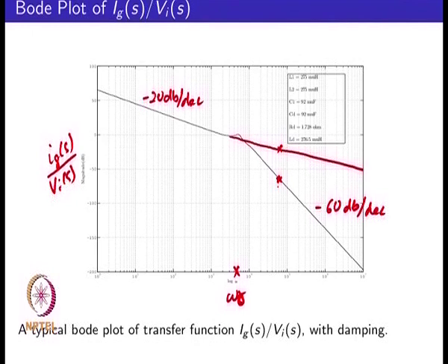So you know that it is feasible to meet the attenuation requirement suggested by the specifications with the LCL filter. What is shown over here is not an ideal LCL filter where the resonant peaks would actually go off to a very large value. This shows a damped LCL filter where the resonant frequency is managed, the gain at the resonant frequency is managed to a lower level.